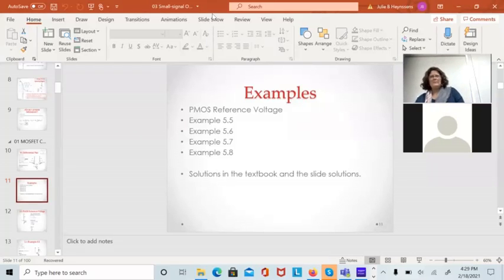Because they're upside down. The first integrated circuit I was ever involved in the design for was an IR imager, the first one optimized for astronomy, and it was all PMOS, no CMOS, because PMOS has lower noise. So to get over the difficulties of using PMOS, we just made the power supplies negative. And then we could draw our circuits right side up.